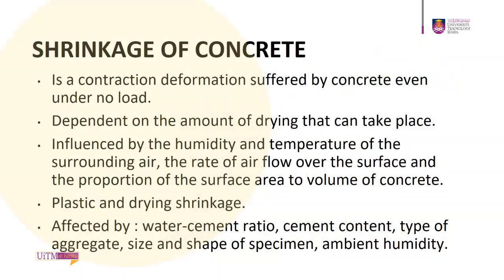Next is the shrinkage of concrete. Shrinkage is a contraction deformation suffered by concrete even under no load. It depends on the amount of drying that can take place, and the shrinkage is influenced by the humidity and temperature of the surrounding air, the rate of airflow over the surface, and the proportion of the surface area to volume of concrete.